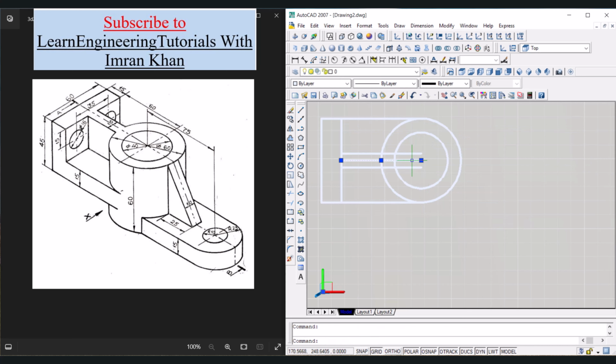Remove this object. Now use trim command, so tr, enter. Click on this object, these two lines and this portion as well. Press escape. Click on line, bring the cursor over to this center point, click, and now in this direction give the value of 75, enter again.